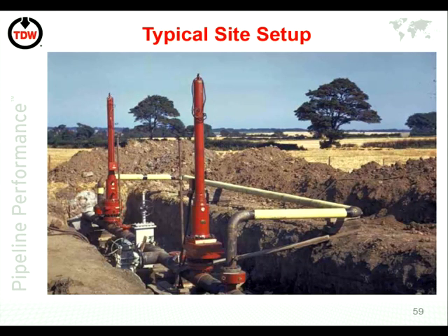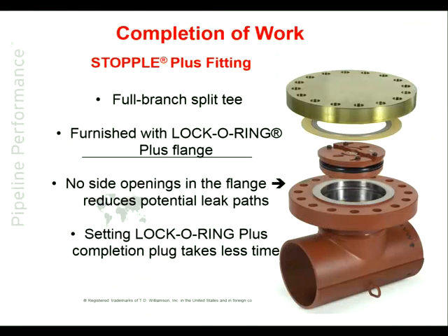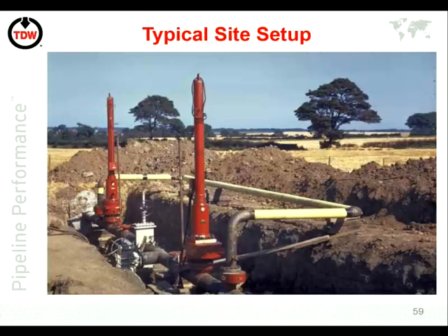The bypass pipe spool, is that brought in by the tapping contractor? Yes, it is. It's brought in, and it's temporary, it's taken away by the contractor as well. So at the end of it, that will be removed and taken away with the machine. But again, it is designed to fit its specific size. It is tested. It is for during the operation. It's an integral part of the pipeline, so it has to be to the same codes, same requirements.